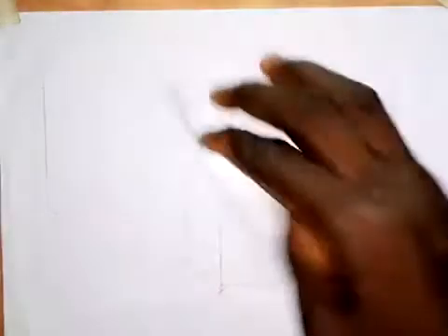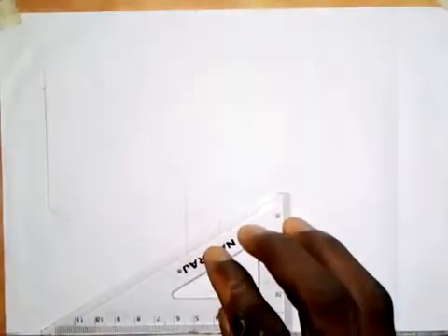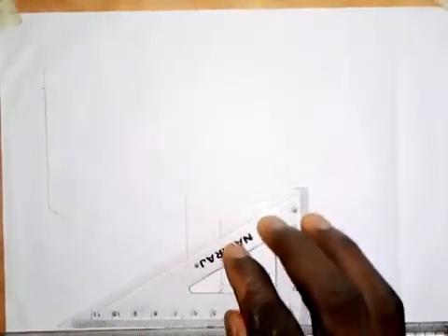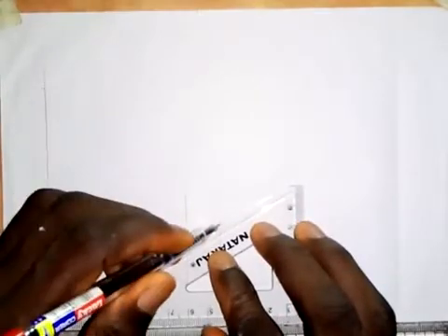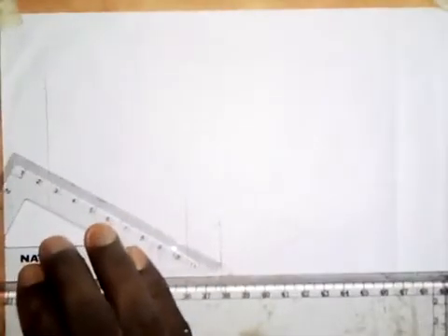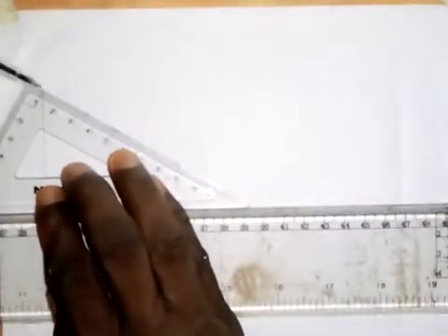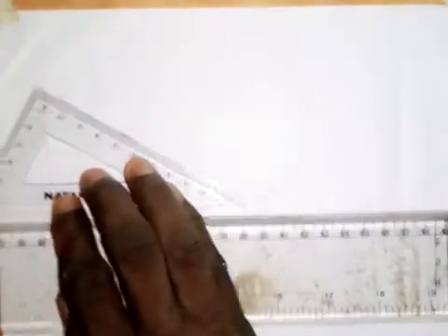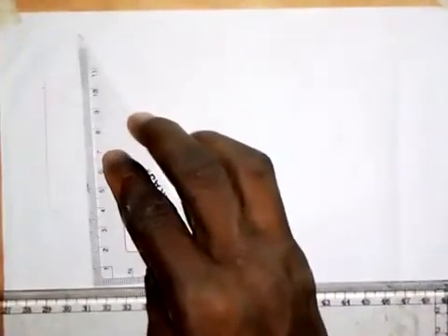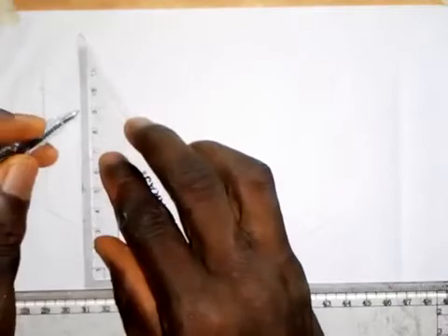All right, so I will transfer. First of all, let's bring out the shape of the front elevation that we are given. I'll transfer this 30 onto this line. Then I will take this to this side like this. Then I'm going to draw a line at this point forward like this. On this line I will take a measurement of 20 millimeters. So this is 20 millimeters here. So I will draw a vertical line down here like this.